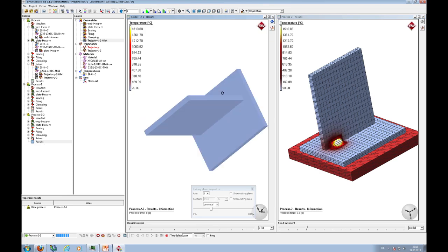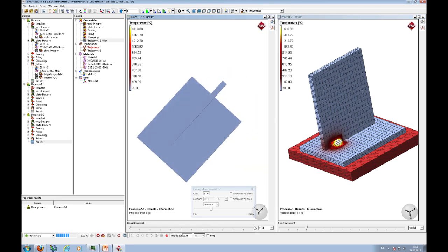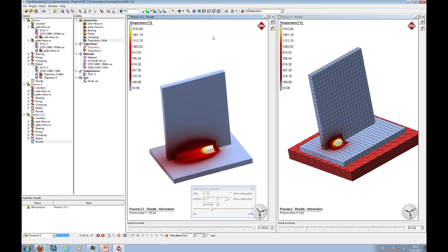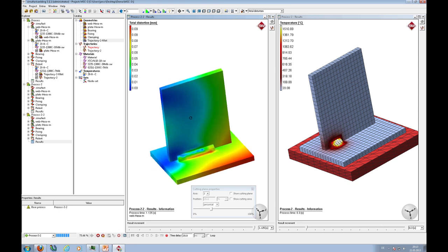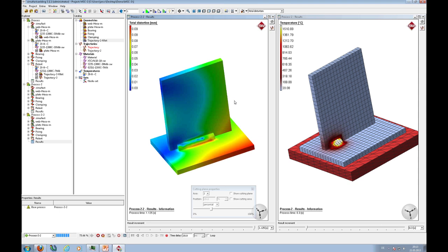Now I hope this calculation still needs to cool down. So after welding, you will get, in this case, a high amount of bainite in your weld, in the end a bit of martensite, which of course influences your distortions, which you want to investigate. Maybe it takes a bit.